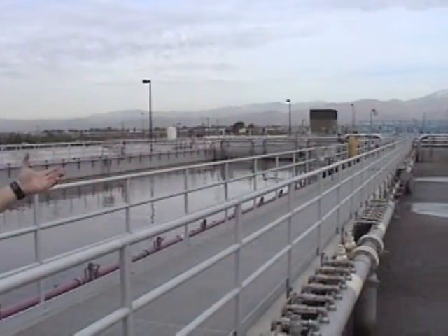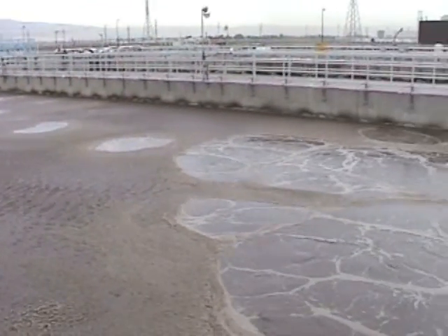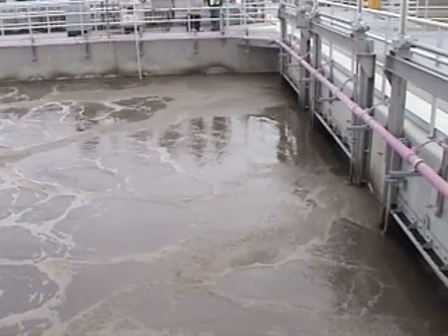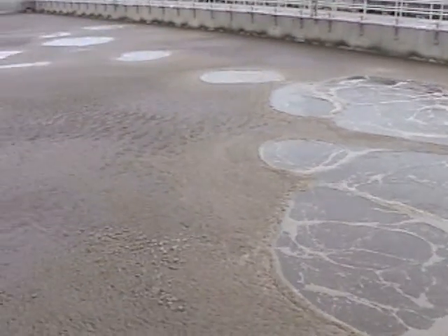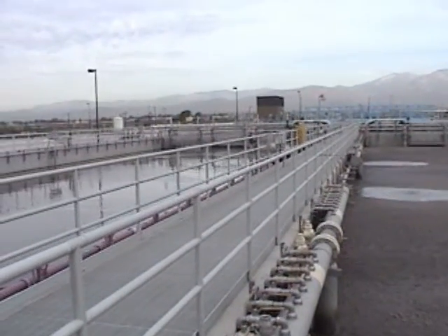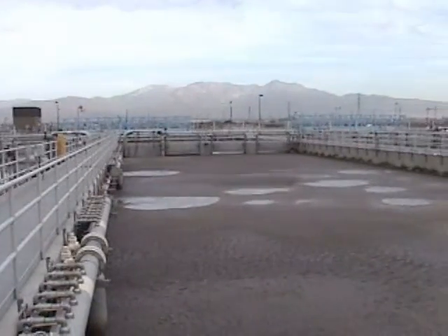Okay, what we want to do to determine the set points for our aeration system is look at our plant effluent data, secondary effluent, final effluent. What we're trying to do here is reduce our total inorganic nitrogen, trying to get that value as low as we possibly can. We want to run the least amount of air that we can through the system because, one, air costs a lot of money to produce, the blowers are expensive to run, and two, in the absence of oxygen, you can reduce your TIN. So what I'm looking at is our TIN values. When I see TIN rising, we'll begin to trim back on the air. But there's a fine balance.